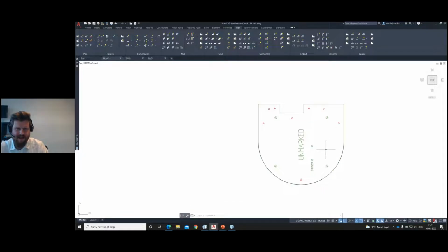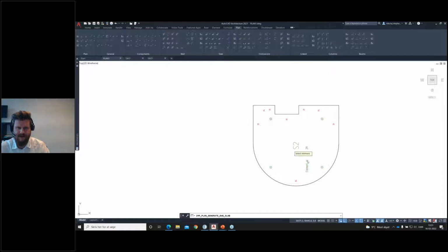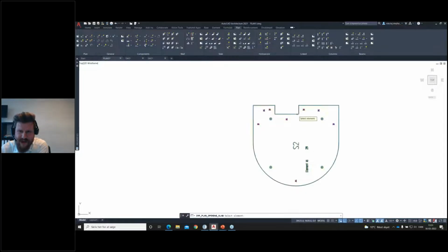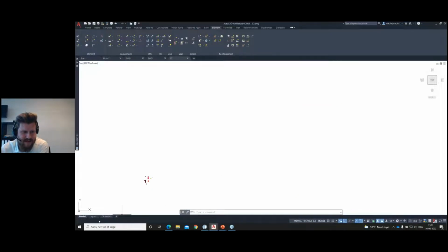And I think I'm going to do it in the shop drawing. I like to do it in the shop drawing. You could do it in here as well, of course. It's the same functionality. We're going to use some stuff over here from Draw MEP key and ducts. So let me just pick this one here, get it saved, get a shop drawing made. There we go. And of course, improved duct diameter and depth location basically means that it's now easier to freehand electric ducts or ventilation ducts inside your precast elements.